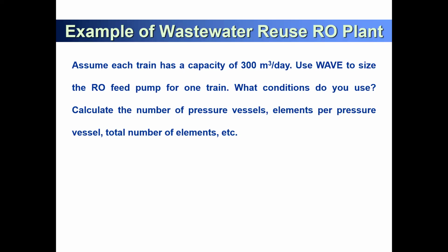So with 50% recovery, our brine concentration is almost double, right? So 3.5% increases to 7%, which is 70 grams per liter of brine concentration. So how about wastewater? The wastewater initial TDS concentration is 1 gram per liter.